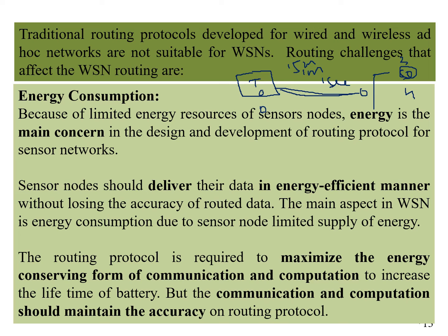If you are using a resolution of 1 second, you will get 3600 values in an hour. While if you keep the resolution at 15 minutes for the temperature sensor transferring the data, then you will have 4 values in an hour that represent the temperature, and it would sense the change.